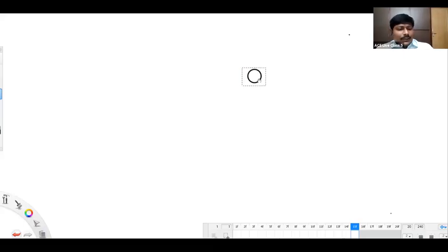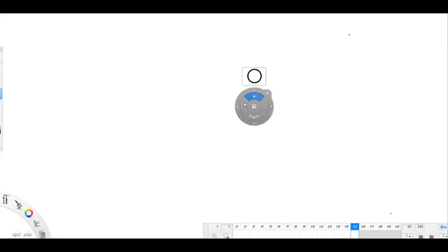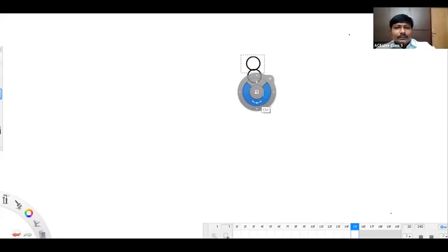For example, if it's a conductor, on each strand we have the skin effect separately. For example, like this, on this strand you have a depth of current, something like this. On this strand also you have a depth of current. Like that, on each and every strand you have a depth of current, right?